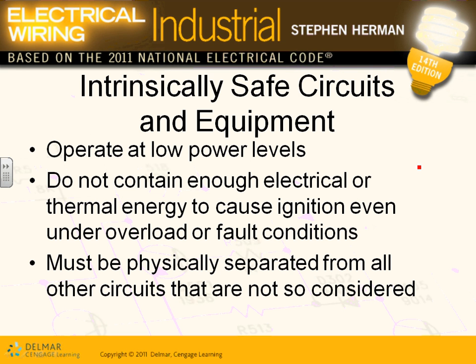You're going to seal as you get closer. You saw a couple of seals, guys, that we do as we get into every piece of equipment that has arcing and sparking, such as circuit breakers and motors. You have to seal within 18 inches of this piece of equipment with a rigid, threaded wiring system and an approved seal for the location. Intrinsically safe systems, you will hear about them all the time.